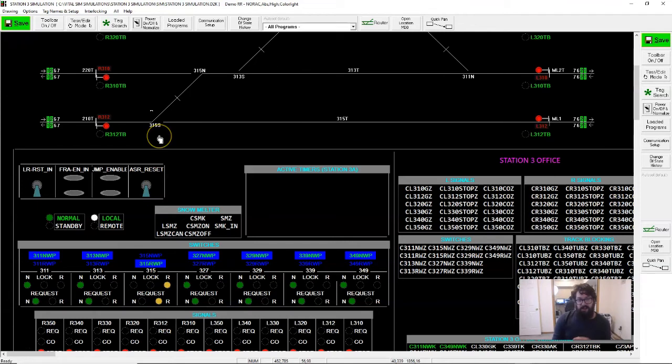Now, as a test engineer for a railway track site, you may want to disable that behavior. You may want to know, for example, what happens if the switch machine is just physically disconnected from the inputs and outputs on your controller. So as an engineer, you would probably expect that the outputs would go high, but that nothing would happen to the inputs because it's disconnected. So let's see if we can get that to happen.